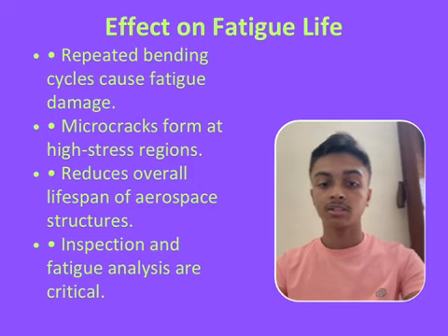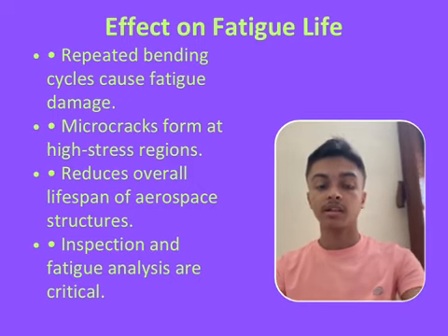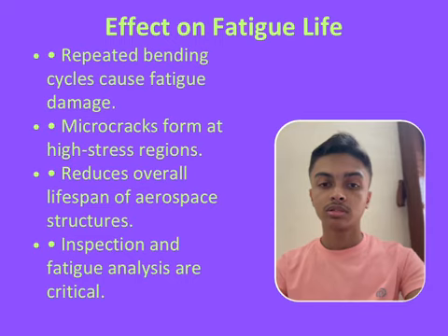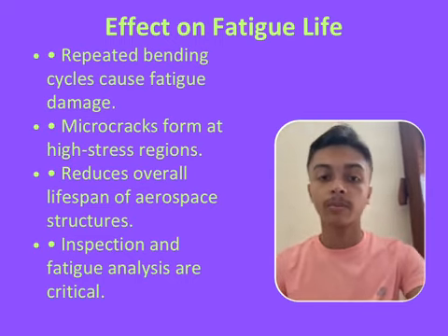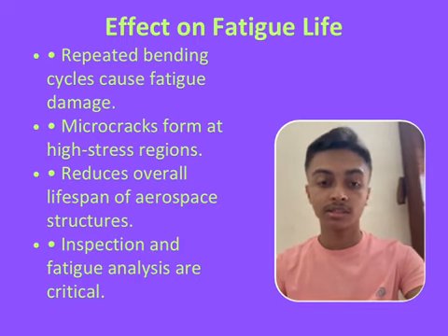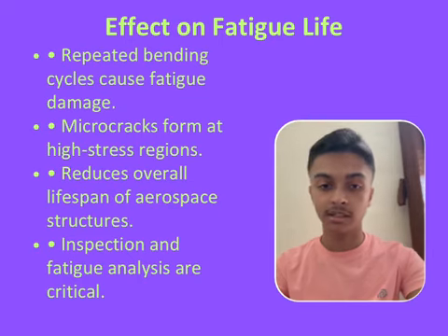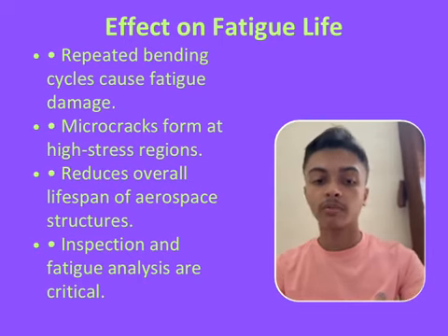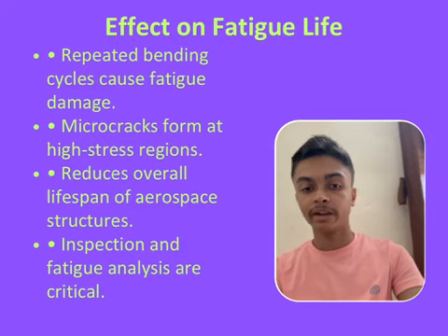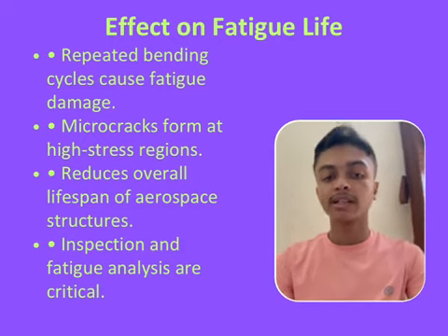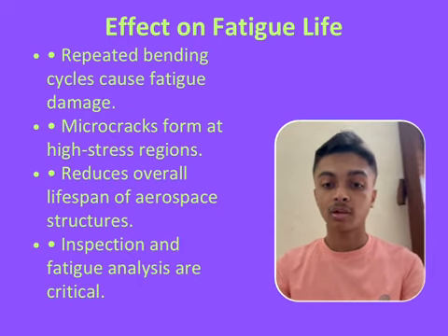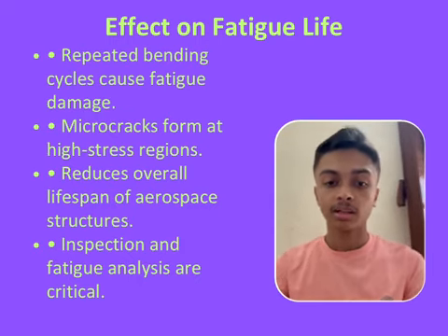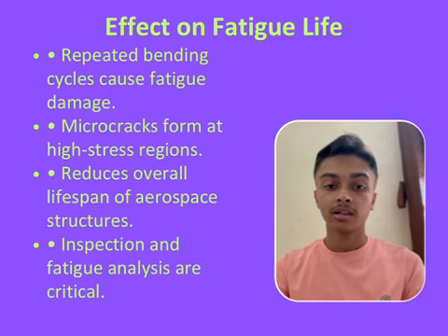Now let's talk about our next slide, the effect on fatigue life. As I said in the previous slide, bending stresses cause crack initiation and fatigue failure. Repeated bending cycles cause fatigue damage.